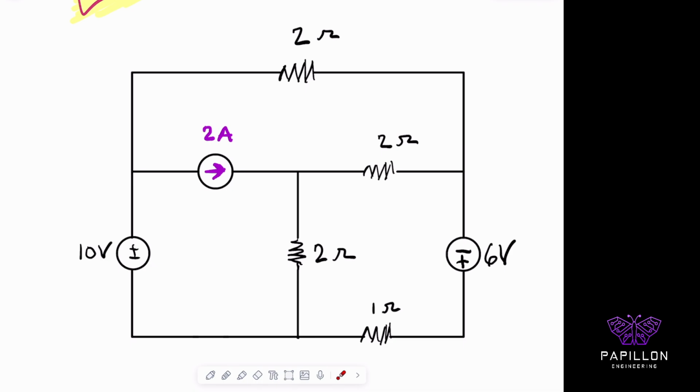You can see now that this 2 amps is over here, but it's going to have a contribution from the current source here, I1, and the current source here, I2, right? But how? To quickly assess it in your mind, you could always replace that current source, at least temporarily, with a resistor. And you'll say, wait a minute, if it was a resistor, then it's definitely going to have a contribution between both loops. But how is that actually happening? The strategy is to think about which node is actually being affected for a problem like this.